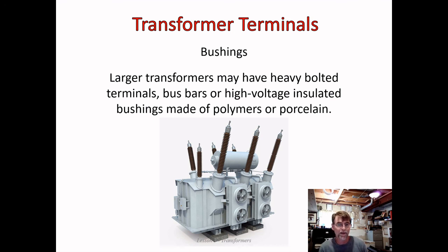They also provide separation from the wire and the transformer itself. So remember, the transformer, you can see it there, is made of steel. Okay, it's all grounded. So you certainly don't want the wire to actually arc to the transformer housing itself. So the bushings offer that protection also. They're very large insulators. They keep everything well separated so that there's no potential for arcing.